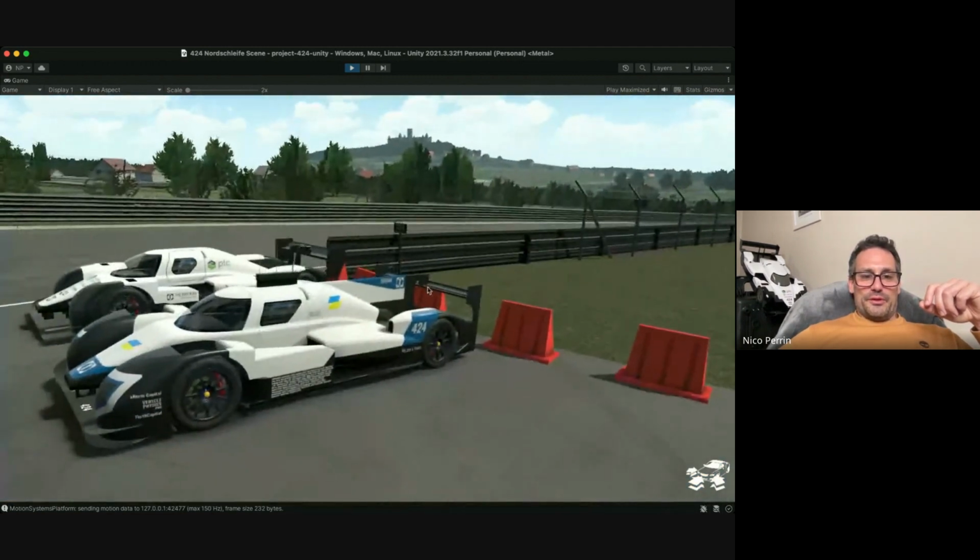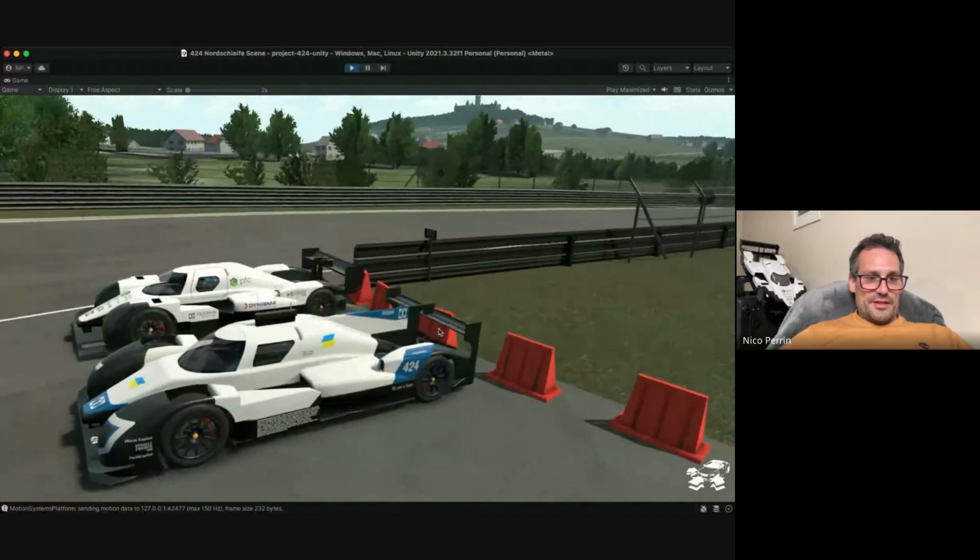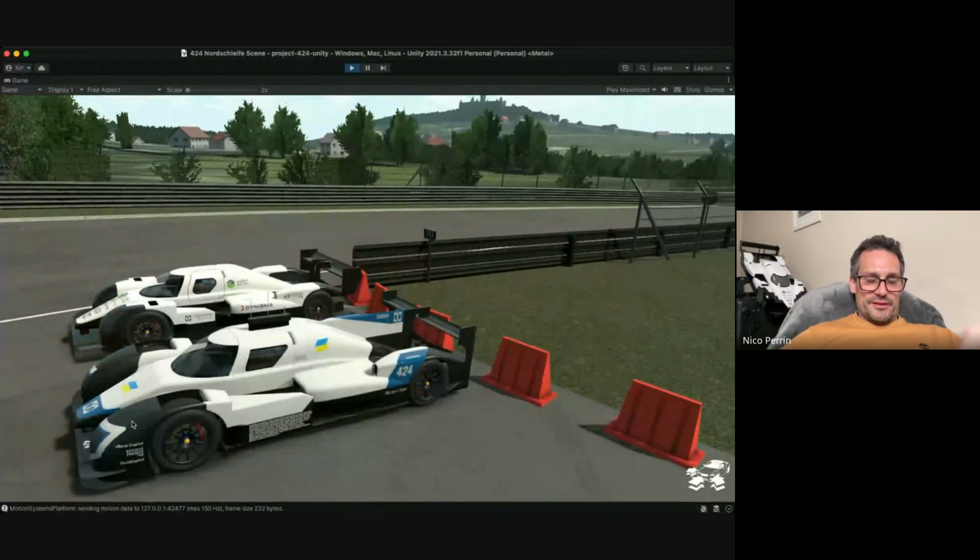And then if you look at the top body, which is the obvious part that people can see and comment on a lot, it matters a bit, but not as much as the front and rear wings. But if you look at the wheel arch, for example, the front wheel arch has much more volume in front of the tire and behind. You see how much shorter the wheel arch is in front and behind. When you do that, it's quite powerful, actually. When you reduce that volume, straight away you create pressure that is pushing down on the splitter or the front wing. It will create more drag straight away.